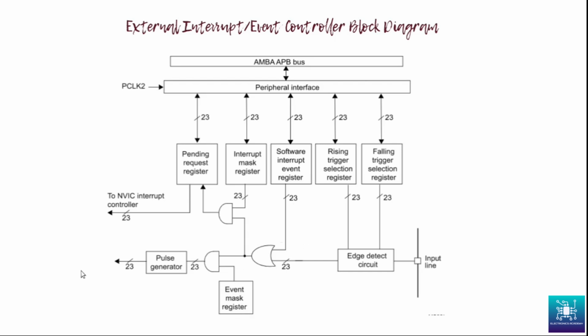Once you are comfortable with coding on this particular board, it is imperative that you start experimenting with these. We will see one scenario here, that is PA0 interrupt enabling, but there are multiple scenarios that you can try out, whether a particular interrupt line can be considered as an event or an interrupt, and follow this diagram all along. This diagram has a lot of information in it. So when you are configuring the registers, if you refer to this diagram, you will not go wrong in configuring your interrupts. And we will follow this diagram when we are configuring our PA0 interrupt also.